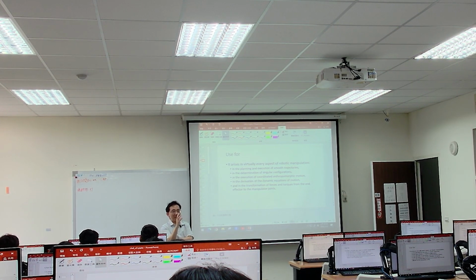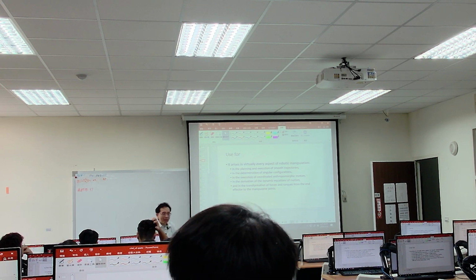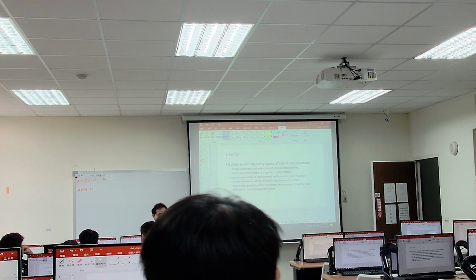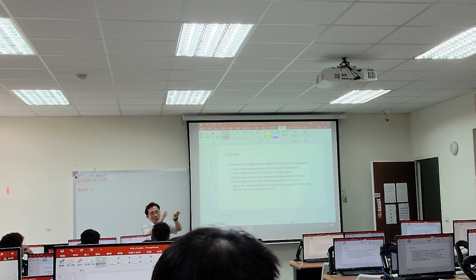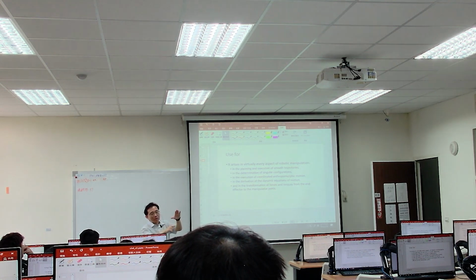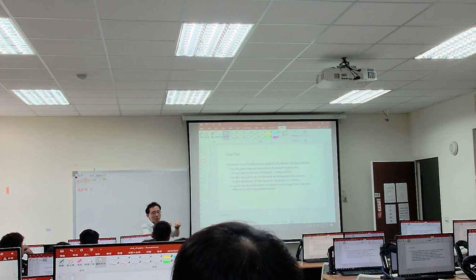And position is not the only issue. Can you look it back? We need to consider the velocity. Why do we need velocity? As I mentioned in the application before, if you need to grind something, if you use the position rule, maybe it can work. But if you can design a velocity trajectory, then it will work as smoothly as you can expect.